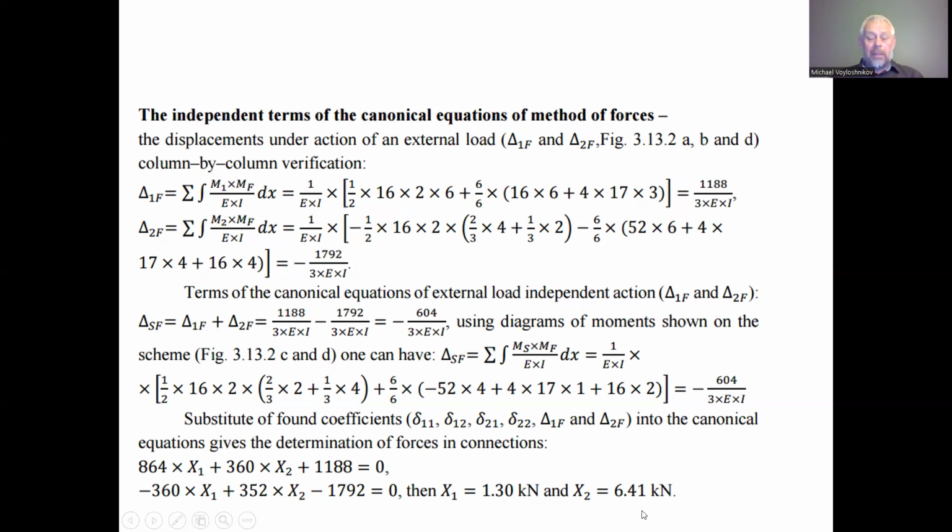These are forces. And now when we have the forces, we can find the other 3 forces. So we originally had a 5 times statically indeterminate system, and we next determine the main system. In the main system, we cut off the unnecessary links of the statically indeterminate system. We have 2. These links were linked from the support to the hinge B, and we substitute these links by the forces found by the compatibility of the deformations. The compatibility of deformation is the canonic equations of the force method.